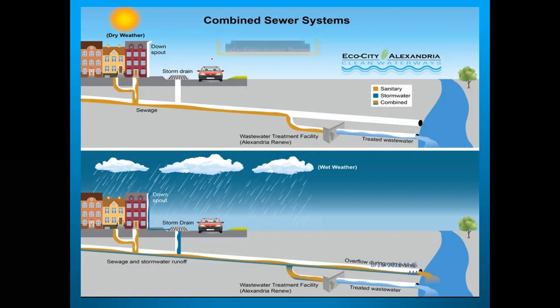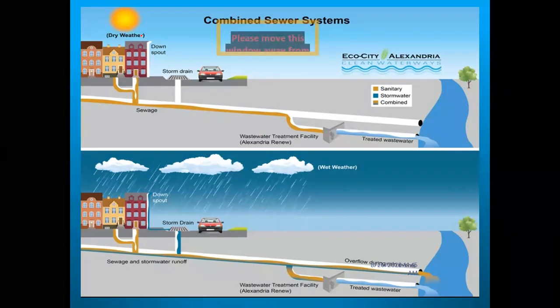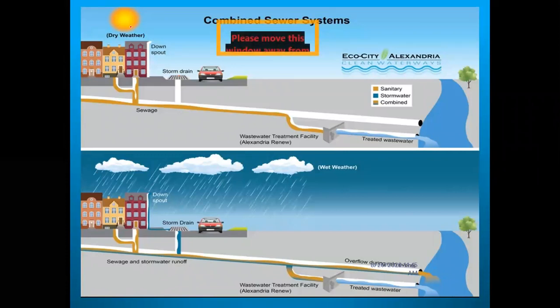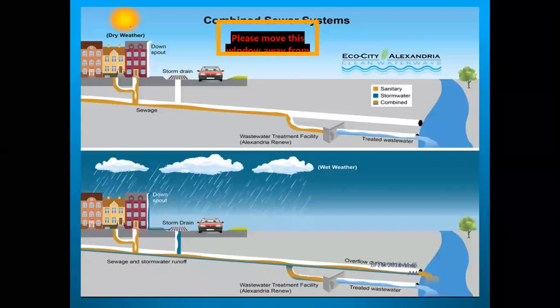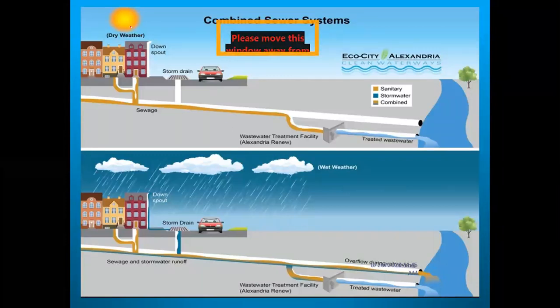Now see the dry weather flow, DWF, and wet weather flow. Dry weather flow means there is no rainfall. Wet weather flow means there is rainfall. So in the dry weather flow, what's happening? See here, from the industry, from the residential houses, apartments, schools and colleges, the general sewage is passing through one pipe. Here there is no rain. See the storm drain.